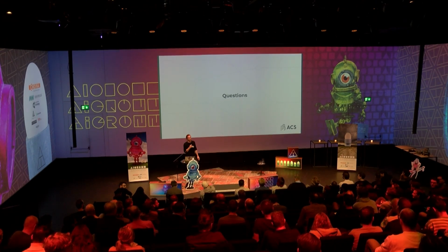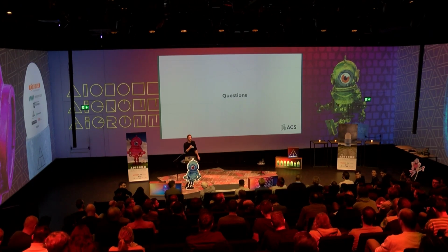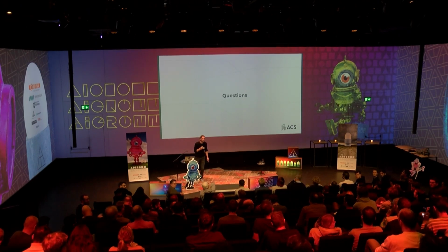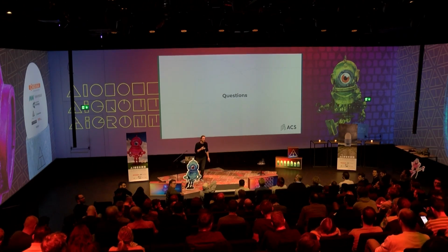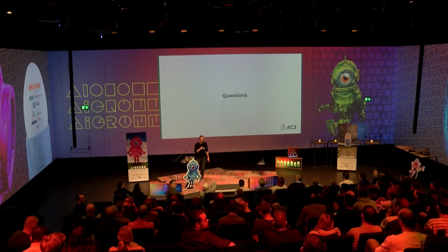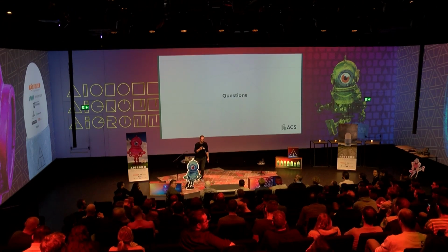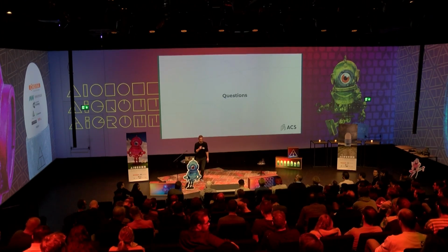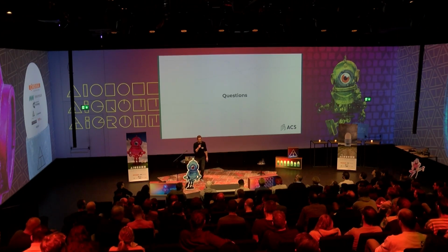So thank you. Rather than learning the impact of weather on a room, why don't you try to learn the parameters from that room? For example, the heat loss, the surface area of walls, the R value, the impact of solar radiation on a room. Because then if you have those static variables, you don't need to retrain the model that often, right? You only need to watch the room for a period of time, and then you can reuse that information all year round. Yeah, it is very good.